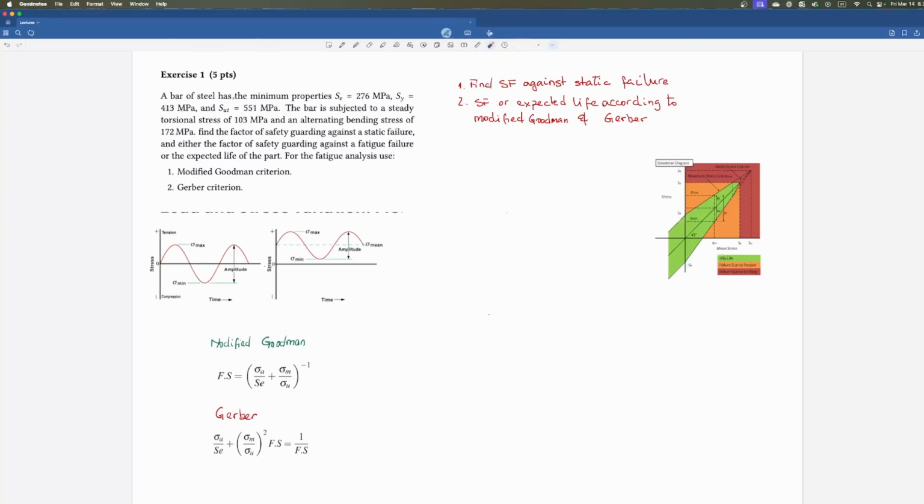Okay. So first, let's take a look at the endurance limit. This one here. If we remember, the endurance limit as it is defined in the lectures is going to be something like this. And then I have the Marin factors here, Ka, Kb, and then continue until Kf, and then the theoretical endurance limit. Now, two ways of seeing this. Already they are giving us, for sure, the practical or the ready-to-use endurance limit. So I don't have to work with any Marin factors because they're giving us it as it is.